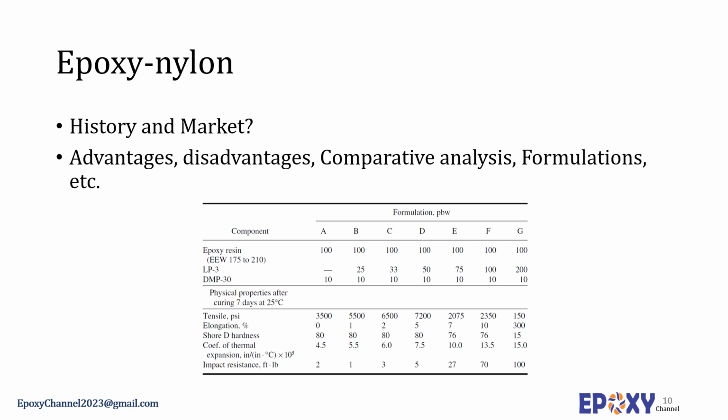Epoxy nylon adhesives' main advantages are better flexibility and a large increase in peel strength compared with unmodified epoxy adhesives. Epoxy nylon adhesives are limited to a maximum service temperature of 85 centigrade and they exhibit poor creep resistance at that. Possibly their most serious limitation is poor moisture resistance because of the hydrophilic nylon polyamide constituents.